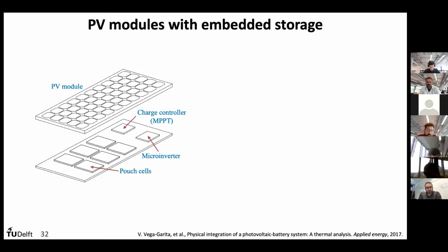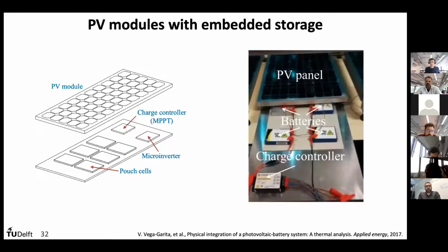Another approach is to integrate the batteries with the charge controller into the solar module, and in this specific case we show a microinverter, a power electronic system that can connect your PV module to the rest of your electrical system. We have also done some experiments with this in the department, so we can enclose all the batteries and the charge controller in this specific case on the back of a PV panel, and we can make a battery. As I mentioned, we also have to take into account the balance between production and demand.